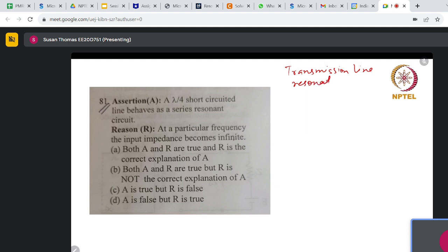A section of a transmission line. Say you have a transmission line of characteristic impedance Z0, a propagation constant gamma, and a particular length of the line L. With that, you also need to say what the termination is: whether it is an open circuit or a short circuit, or a load ZL, or matched to an impedance Z0.